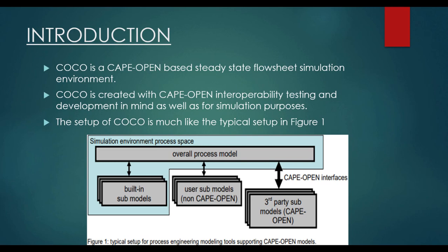The first one is the accumulation is equal to input minus output, means the material which is entering into any equipment or something like pipeline, vessels, columns, and the material which is now a product after being processed through the unit. So you put input minus output is equal to accumulation, but for the steady state you set accumulation to 0, so your input must be equal to output. So that's the material balance at the steady state.